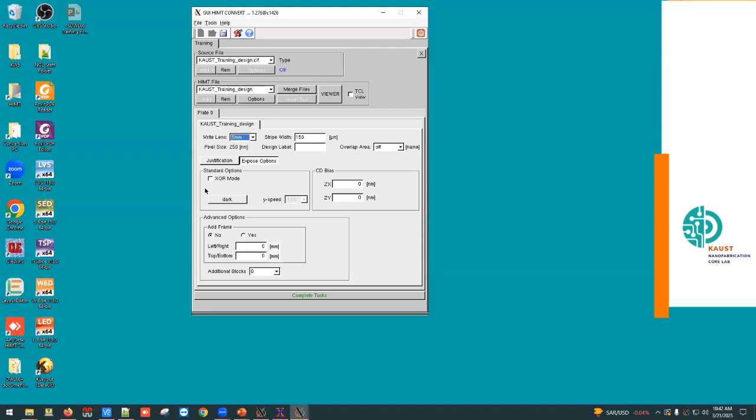So you can design in your software as you wish. If you want to have 50 layers in your design, I don't care. And it's not going to affect. But when you export exactly the layer that you want to expose on that substrate at that specific moment, you just need one layer.